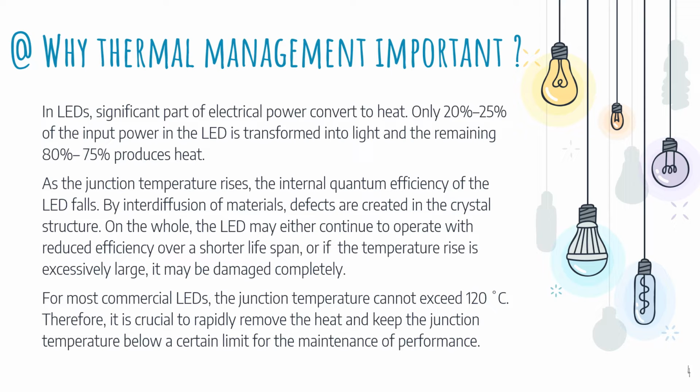For most commercial LEDs, the junction temperature cannot exceed 120 degrees Celsius. Therefore, it is crucial to rapidly remove the heat and keep the junction temperature below a certain limit for the maintenance of performance.